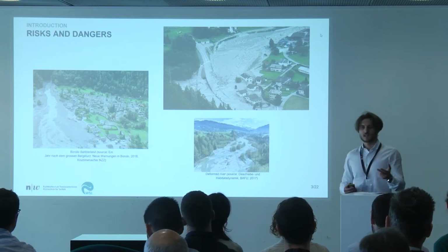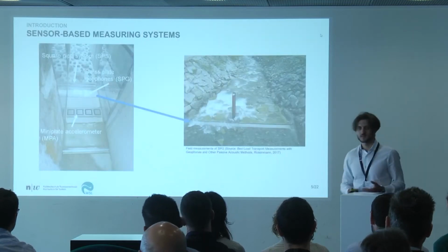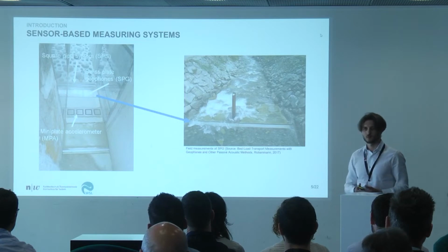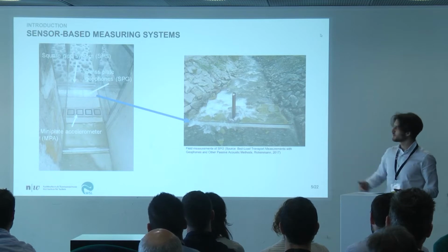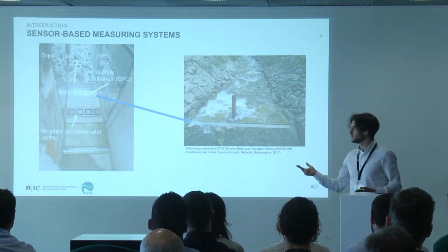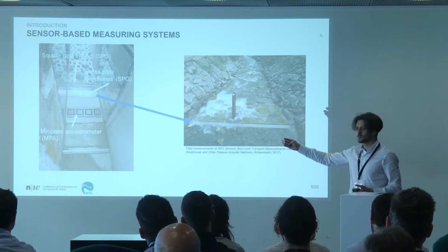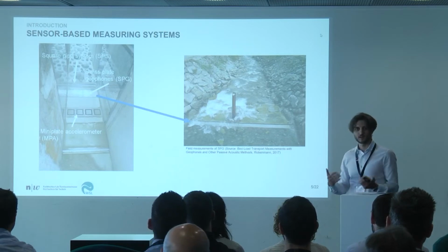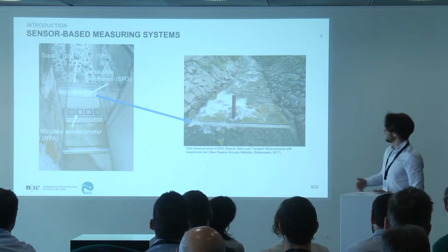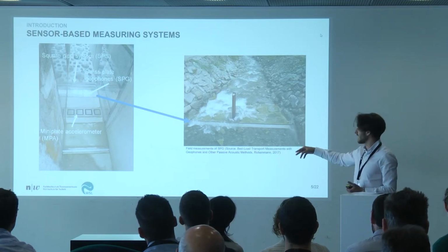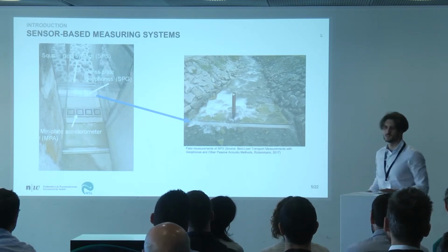If you ask yourself now whether it's possible to measure such bedload transport, yes, it is possible. Our project partner, the WSL, developed 3 measuring systems, as you can see on the left image. There is the square pipe system, SDS, the Swiss plate geophone, SPG, and the third, the mini plate accelerometer, MPA. On the left image, you can see them installed in the artificial flume, where they conduct controlled experiments to collect data. For the SPG, we also have a picture of how it looks when it's installed in a Swiss mountain stream here.